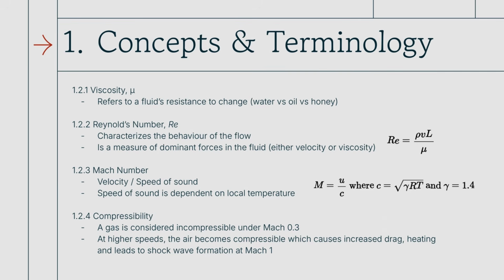And then the last one is compressibility. Liquids are not very compressible. Solids, definitely not compressible. Gases are compressible. Under Mach 0.3, generally we consider them incompressible. That's not really the case, but it's a good assumption.